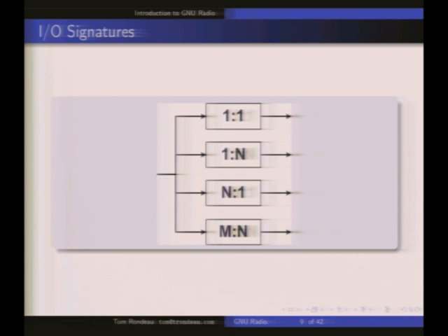The other thing to think about is in software radio, and really in any communication system, sample rate changes are really important. So multi-rate signal processing is a huge deal. Generically, GNU Radio supports four abstracted signal processing block classes. The standard one is the one-to-one: you have one sample input, you produce one sample output. Then you have the interpolators. You come in with one sample and you produce n samples out, so you're interpolating your signal in some way. You can think of all of these in terms of filter operations. If you think of an interpolating filter, you're adding samples to a stream.